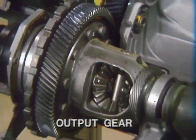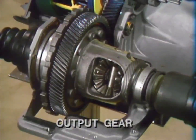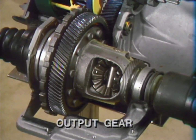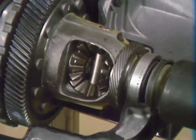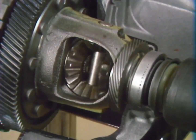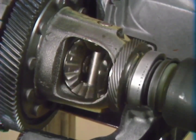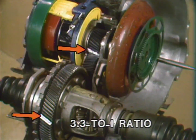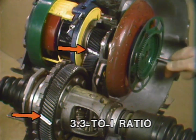The output gear is attached to the case of the differential, which also is supported in the transaxle by 2 tapered roller bearings. The differential works just like a rear axle differential, except it is part of the transaxle and it drives the front axle shafts. Now follow these marks on the input and output gears as we demonstrate the final drive gear ratio, which corresponds to the rear axle ratio on rear drive cars.